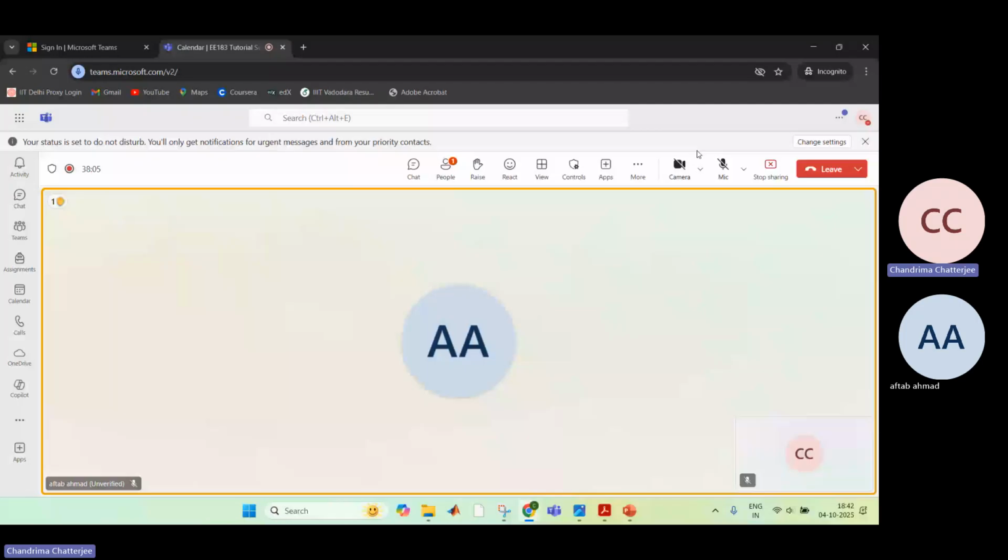Now, initially, the STATCOM was injecting 400 kVAR, right, when the output voltage VC dash was 1.05 per unit. Afterwards, the STATCOM injects 500 kVAR, okay, an extra 100. What will be VC dash? Okay, that is the question. So we can write what is constant. So we can write like this: